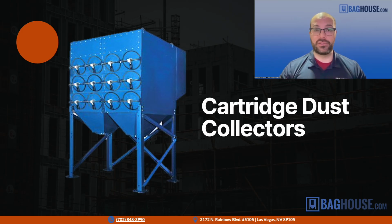This picture here you'll see is a standard horizontal design where the filters go in horizontally. Others use vertically oriented filters. But in both styles, they basically mimic the baghouse where dirty air comes in, is captured on the surface of the cartridge, and then clean air exits through the back of the cartridge collector. Just like a baghouse, it's just rotated the orientation a little bit.